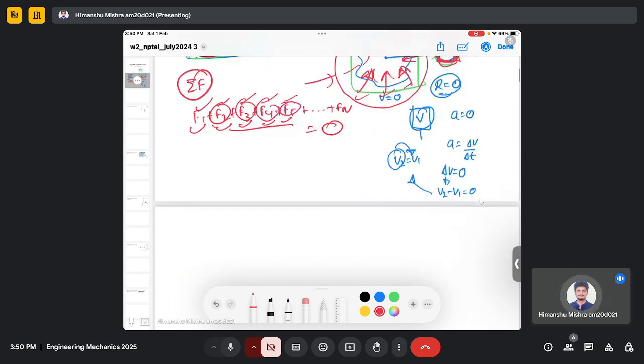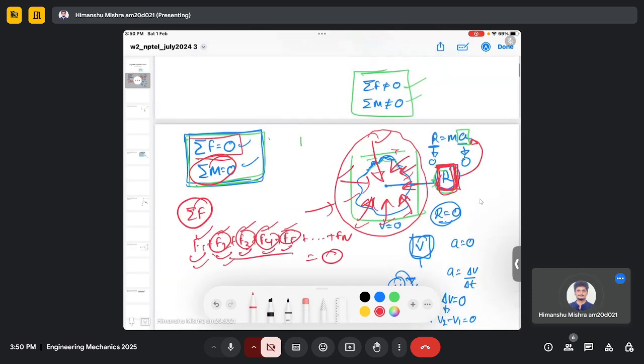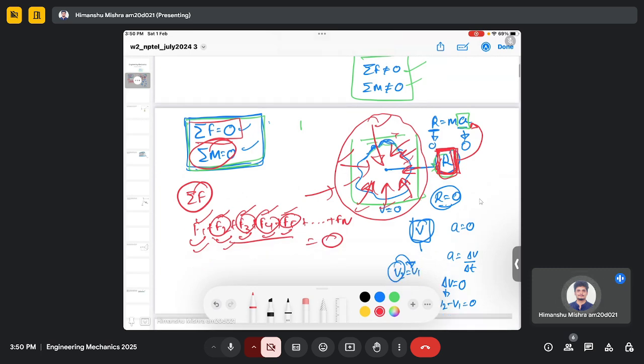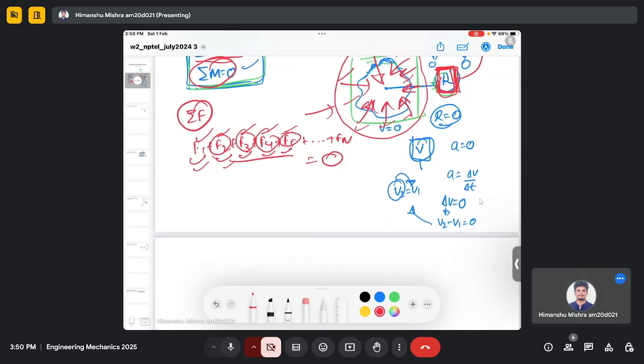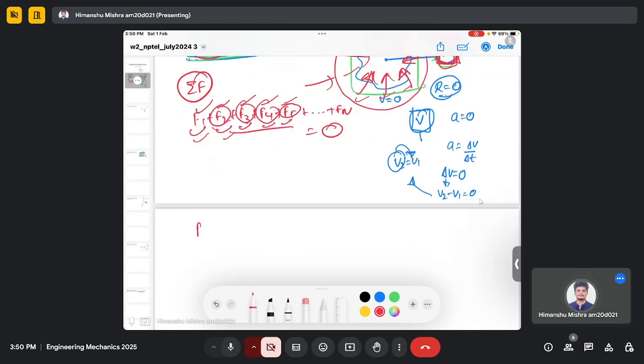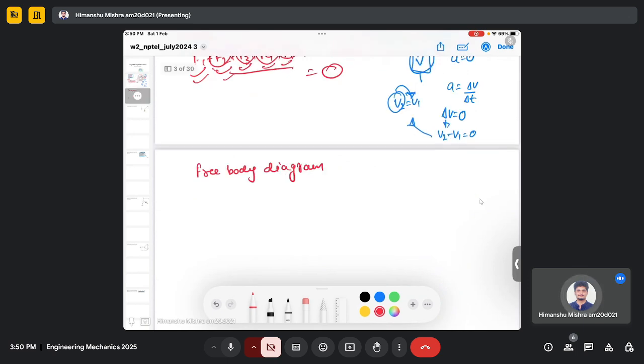Now in order to calculate all these internal or individual forces, we actually need to make the free body diagram. For the moment case, we are very clear about the two situations: first to calculate the perpendicular distance and then to follow the sign convention. In these kinds of problems, our first objective is always to draw the free body diagram. So for example, let's say you have a system in which you have multiple members given here.